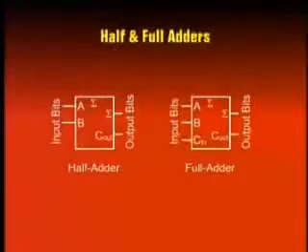The diagrams represent a full adder and a half adder. A single bit binary adder circuit basically adds 2 bits and a carry bit, generated by the addition of least significant bits. The output of the single bit adder circuit generates a sum bit and a carry bit. An adder circuit that only has a 2-bit input representing the 2 single bit numbers A and B and does not have the carry bit input from the least significant digits is regarded as a half adder. An adder circuit that has 3 inputs, 2 bits representing the 2 single bit numbers A and B, and the third bit representing the carry in bit, is regarded as a full adder.